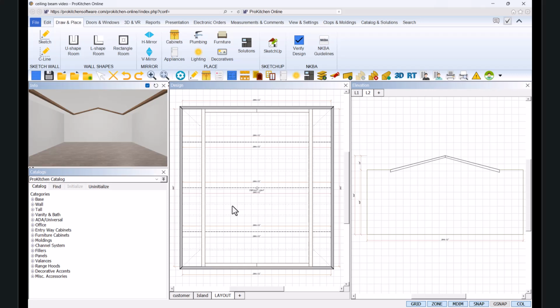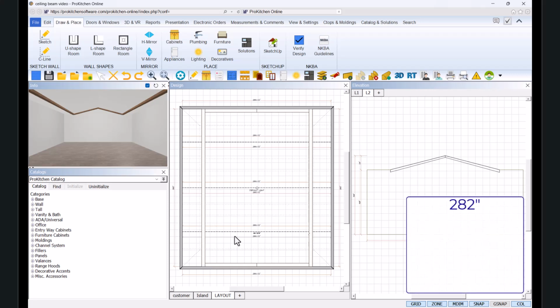Before we create elevation views, copy and paste, and make final edits, I will want to make sure these construction lines are spaced in such a way that the empty space between the beams are equal. Time to do a little math. I have a room at 282 inches in depth, minus the 6-inch depth of the south ceiling beam, which will reflect a face-to-face placement of beams in the 4th section, instead of face-to-back placement in the other 3 sections.